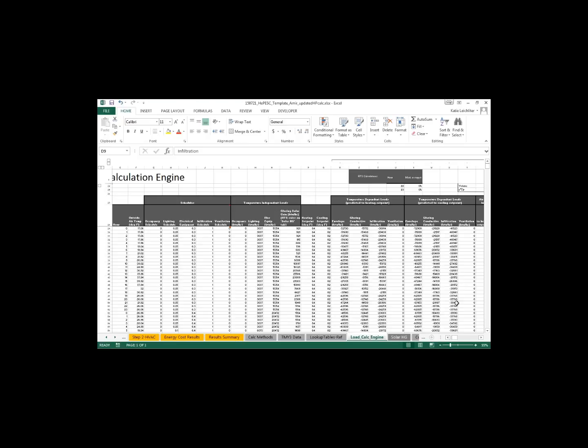We have the load there, so we might be able to pull off a percentage and say this percentage is going to ventilation, but I guess we haven't included anything in the tool that would separate the calculation for dedicated outside air. You can specify the ventilation rates, and they're all included in the heating and cooling. Yeah, all that air heating and cooling would just be on the coils.